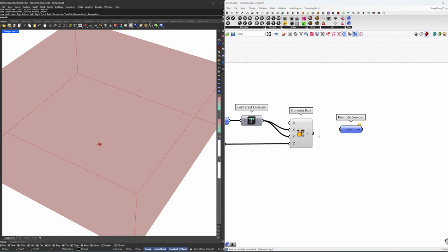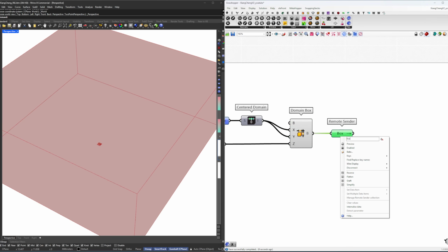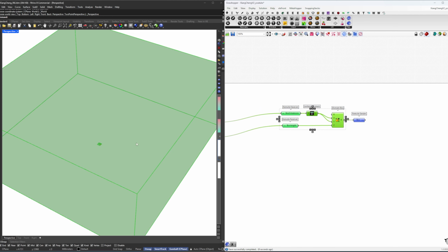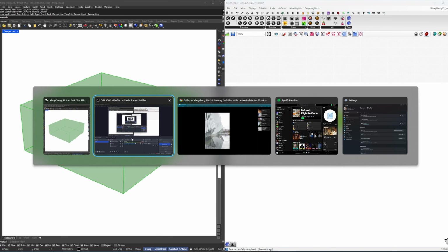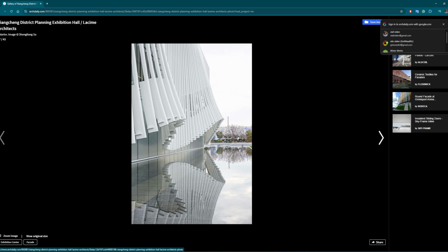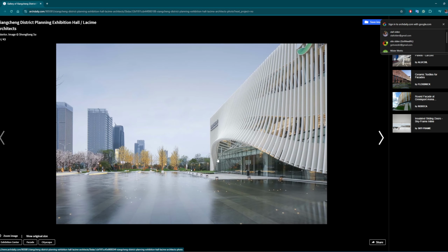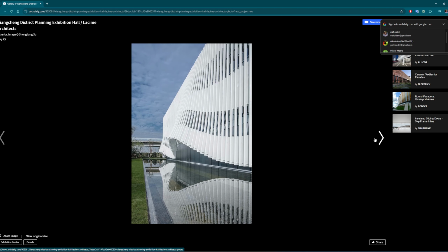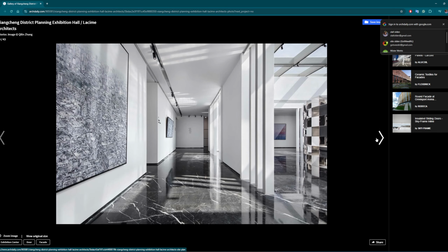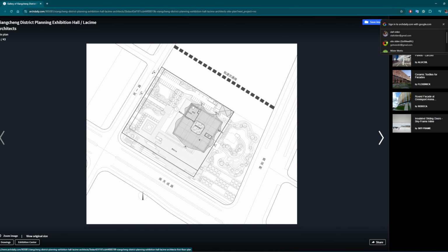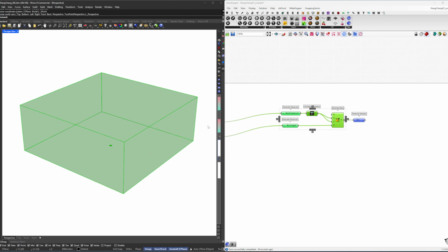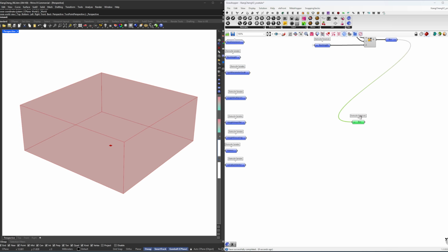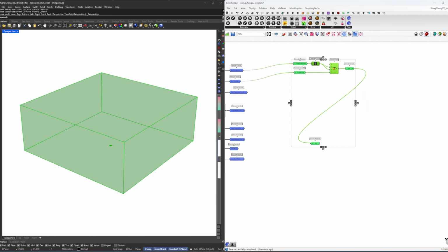This is a little bit the first step. Let's create a variable that says box. Basically this is the base shape of the building. It is the shape that's going to host the facade that we're going to dive into now. It's the host where we're going to make this nice curved facade, both in a vertical and also in a horizontal dimension. And here is actually what we're going to create, and also the box main shape which we just made. So let's go back to the script. Let's bring this guy in. Let's give everything a bit more space.